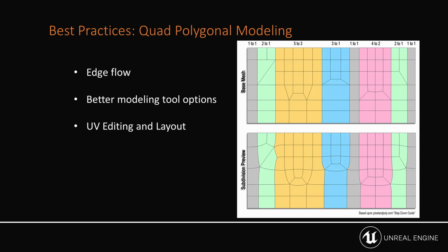Now, with that said, that's not always possible, right? But by all means, if you can keep it to a quad-based workflow while you're working, this is going to provide a much easier way to clean up the mesh as well as UV layout and any changes that might need to be made while working away on the data.